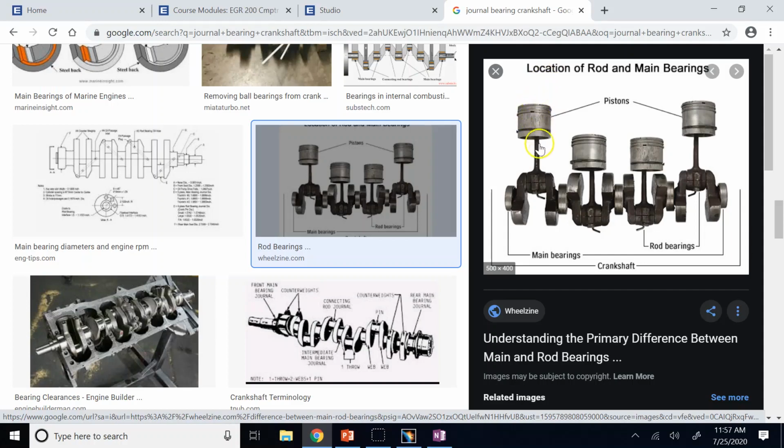The piston applies that force through the conrod on what? On the crankshaft. And the crankshaft would apply that load to what? To the bearings it is mounted on. And these explosions happen very fast. When the piston goes down, the force goes down because the expansion happens, so the force does change versus time. When they come up again and the explosions happen again, there is another force.